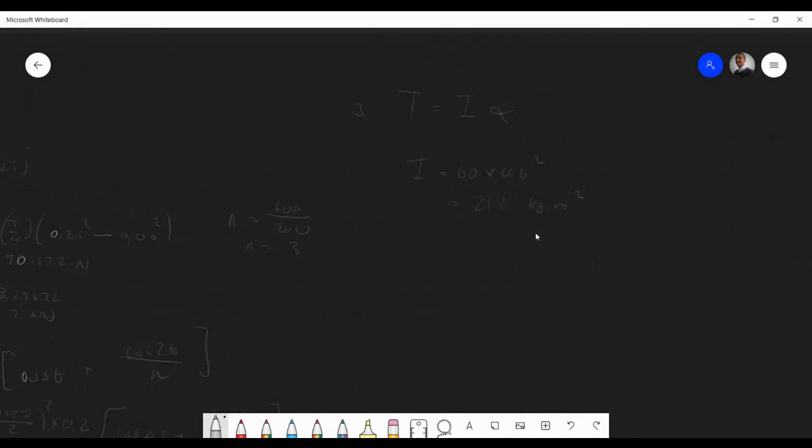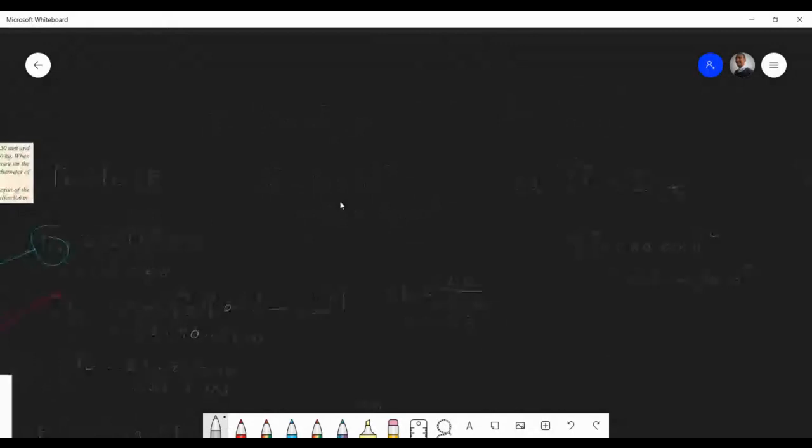Let me just show you. Let's first work out the resisting torque, so that's on the engine side. It's P times 60 over 2 pi. All we're really going to end up doing is finding that torque and subtracting the other torque, the 39 something, from the new torque we got here. So yeah, that's basically all.